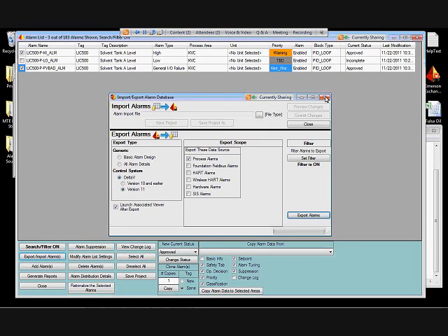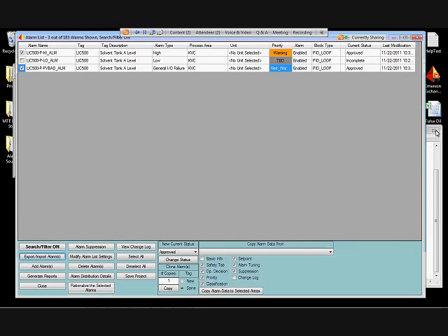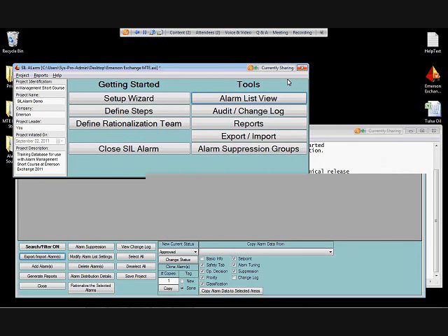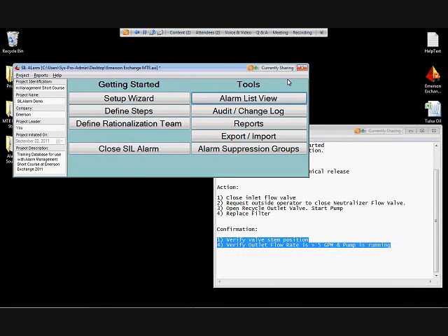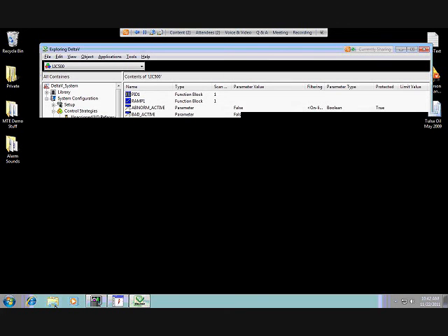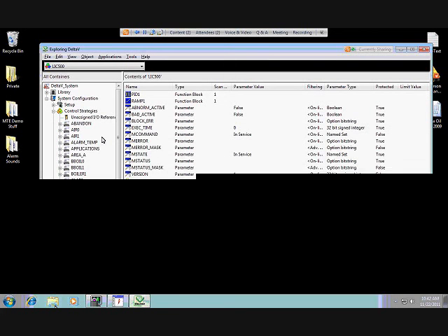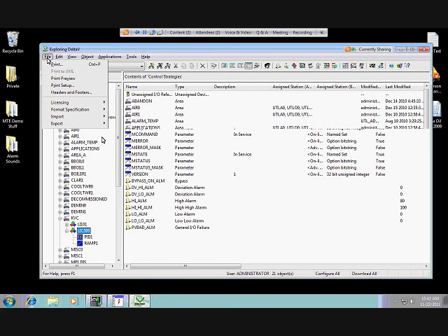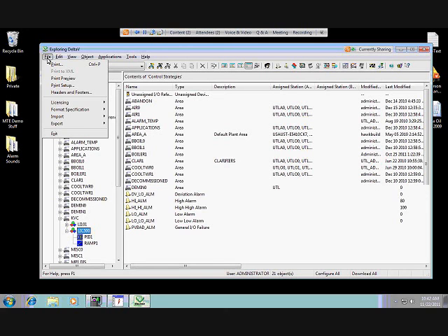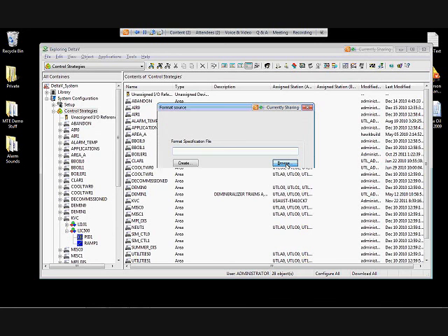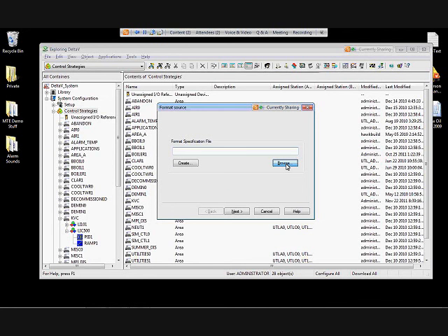Thank you, Todd. At this point here, we have an approval and everything is ready to go. So I'm going to return to the DeltaV engineering environment and import that set of approved changes. So File, Import, User-Defined Format, and browse to that FMT file, which is going to take and interpret that TXT file.